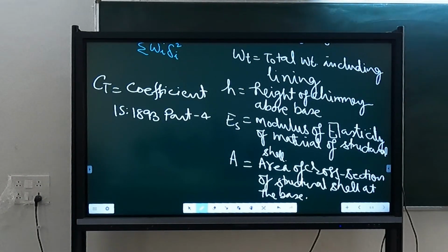It says 5% for steel, 5% for concrete, and 7% for brick masonry. But the modification has given in a table. It has given different damping at BE and MCE. I don't know what they will do with the damping at MCE, but they have given. Okay. And for steel it is 2%, reinforced concrete 5% at BE, and brick masonry 7% at BE.